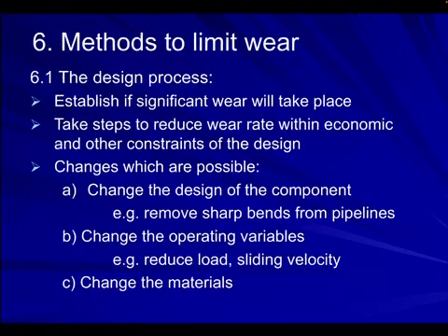So how do we limit wear in the design process? First we need to establish if significant wear will take place. Then we need to take steps to reduce the wear rate within the economic and other constraints of the design. Changes which we can do are the change of your component, remove sharp bends from pipelines, for instance, or change the operating variables, maybe reduce the load or the sliding velocity. And then lastly, of course, it's very important, the change in the material.